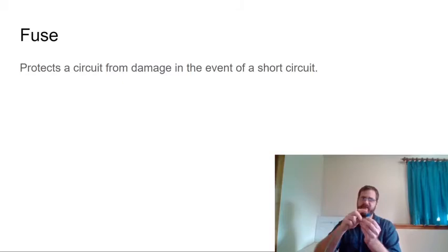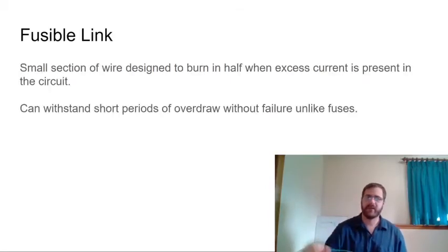So if you have a vehicle that blows fuses, I hate to say this, but fuses do sometimes get old and kind of corrode inside and blow for virtually no reason, but that's not usually the case. Typically, if a fuse blows, you've got a problem. So that turns into diagnosing wiring systems.